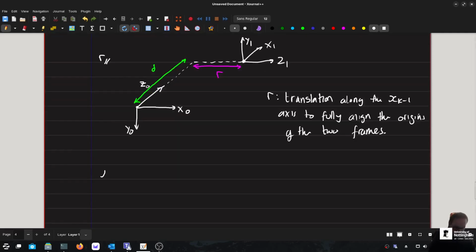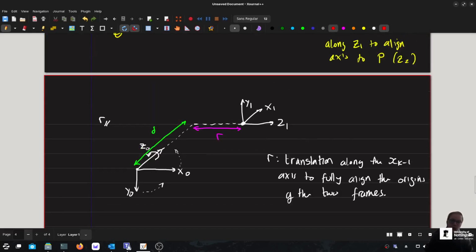When it comes to alpha, the twist action, you can think about where we've done the rotation, our theta. It could be a rotation like this, just some frames in this case. But let's imagine that I did rotate the axis around the z. Let's imagine this first point was a rotary axis. I will go back to the previous example anyway. If this rotates, then of course this x0 would rotate, and y0 would rotate around. But in turn, the origin of the next one would also rotate. It will go all the way around like so, won't it? If you did a 90-degree turn, for example, then this origin would rotate around like so, and then all the frames would have been rotated.